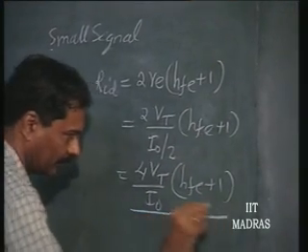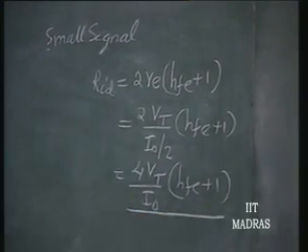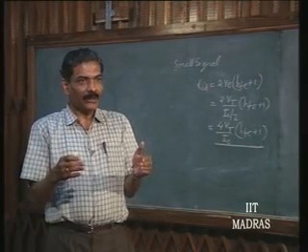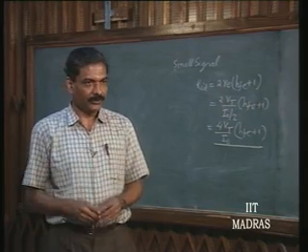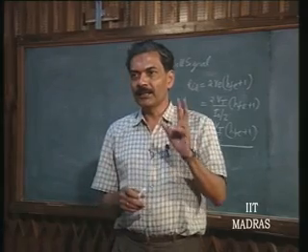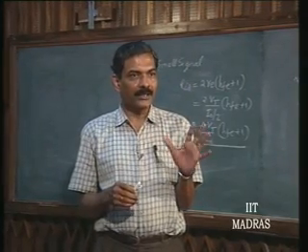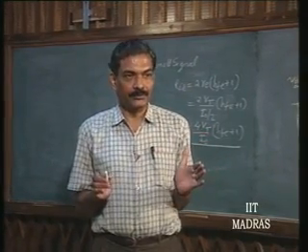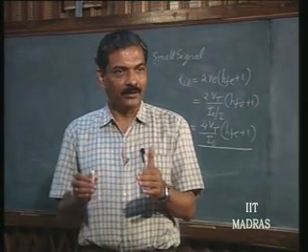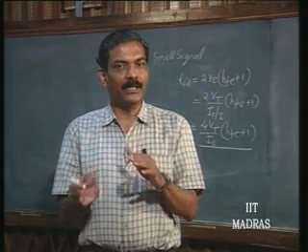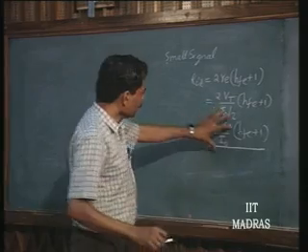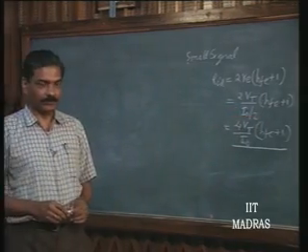So, this is one of the design parameters. You might be required to design this as an input stage, at which point of time you would like to know what the input impedance of the stage is. As I earlier pointed out, the input stage has the primary responsibility of taking care of input impedance. The priority that you give to the parameters of the differential amplifier itself differs depending upon where exactly you are using it. So, in this case input impedance is a very important small signal parameter.